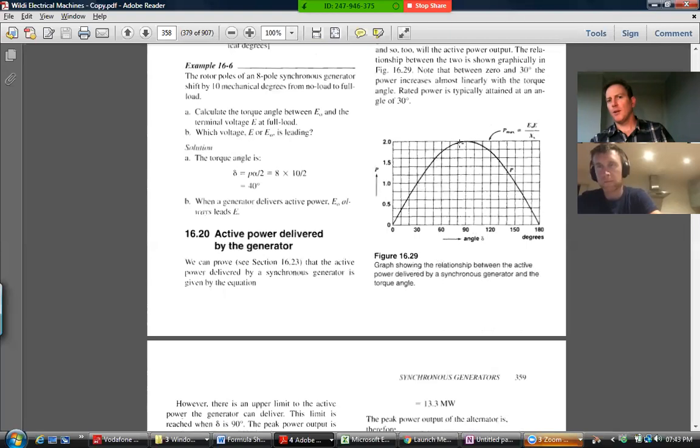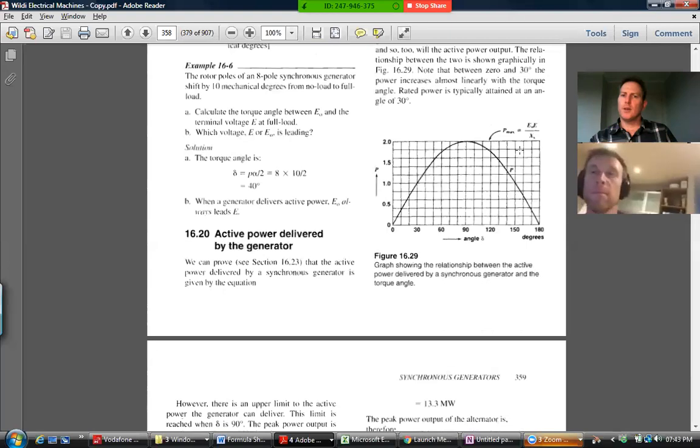Eventually you get to a point where you open it some more, and suddenly you can't absorb all that energy into the grid. Meanwhile, the steam turbine, because you can't deliver as much power and can't push as hard, has nothing to push against. So it will just accelerate like crazy, and this thing will spin radically faster than the synchronous speed and induce a whole lot of current and blow things up, and some circuit breakers would have to act pretty quickly. So you can't utilize this area here.